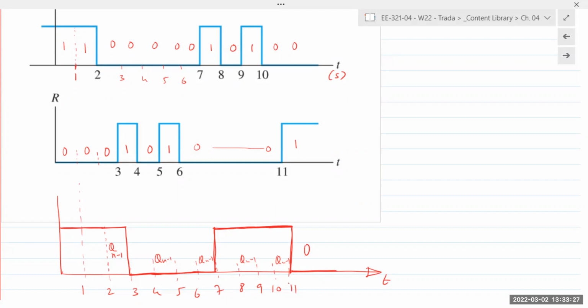You have to remember, in all of these digital circuits, you will use a transistor as a switch. So when it goes plus 5 volts, depending on how it's configured, you're operating the transistor between saturation, cutoff, saturation, cutoff. So 0 current, max current, 0 current, max current. Depending on what you're using the circuit for, that's how you configure it. But for any logic circuit, this is how you would determine the timing diagram. If some students are taking the labs, you have already had some experience with timing diagrams. All right, any other questions?